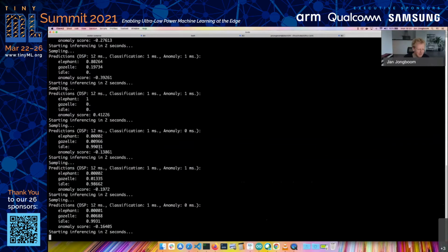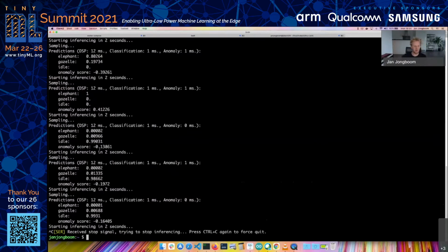But really great. Okay, so we figured, for basic stuff, this works. It's really, really fast. It's 14 milliseconds, 13 milliseconds to do the analysis for over a second worth of data. So it's great. You can basically be in sleep mode or in very low power mode, and just get data from the accelerometer the rest of the time.